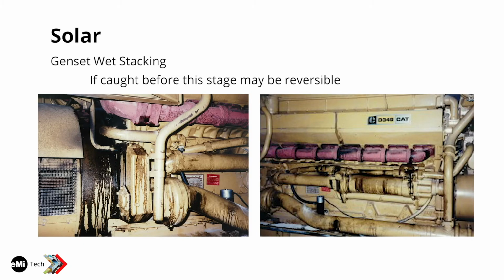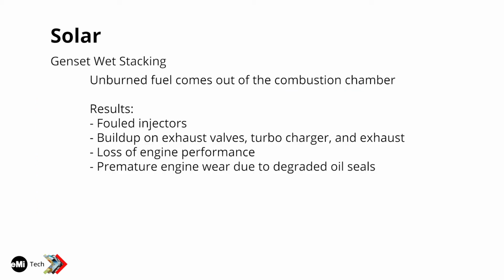This is what wet stacking looks like if it's let run. You get oozing black coming out of everywhere on the generator. If it's caught before that stage, it can be reversible. Basically what it is is unburned fuel that comes out of the combustion chamber, and it results in fouled injectors, buildup, loss of engine performance, premature engine wear, and degraded oil seal. So it really causes a lot of damage to the generator, so you don't want to go that direction if you can help it.